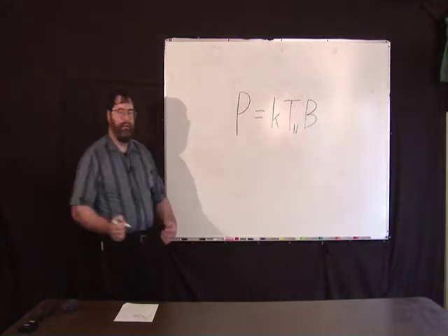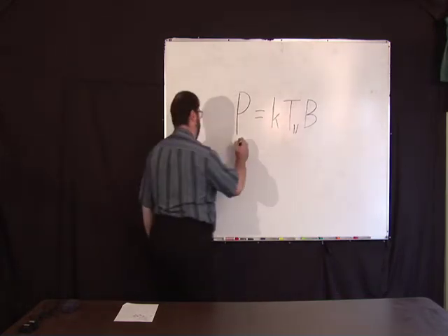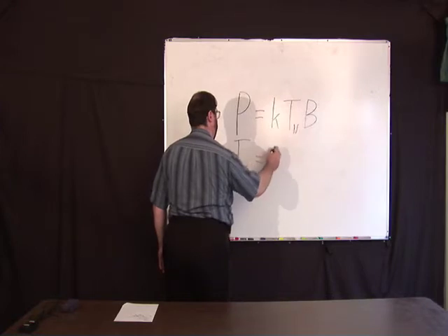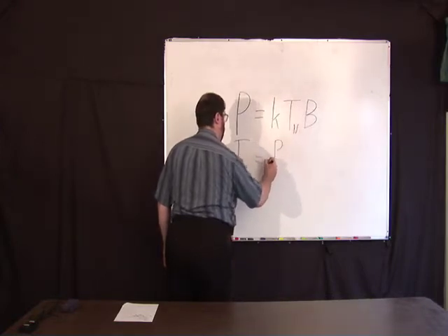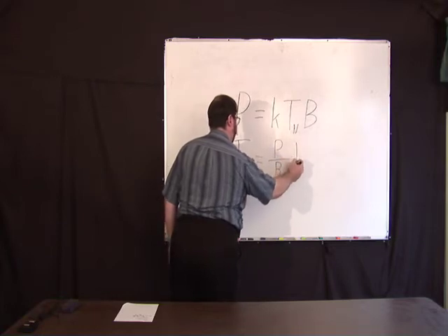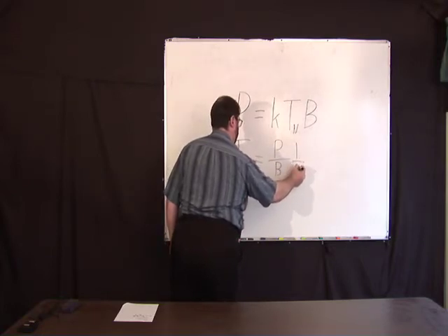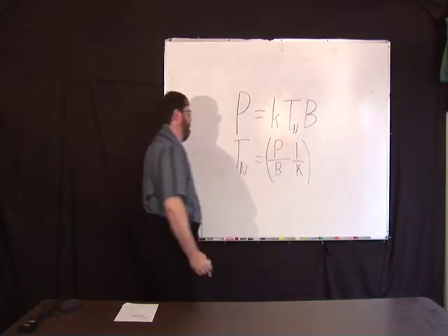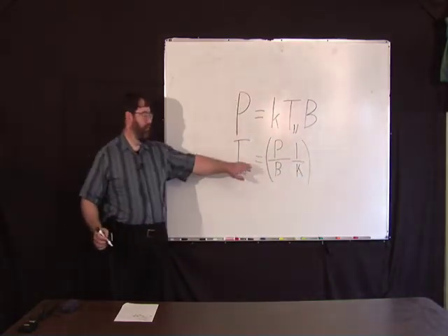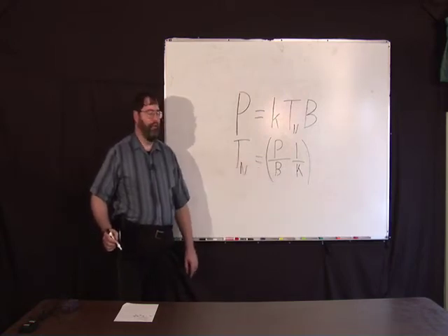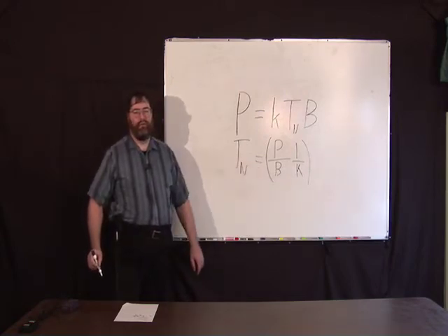Okay? The noise temperature, doing a little algebra, is defined as the power per unit bandwidth divided by Boltzmann's constant. So you measure some power per unit bandwidth, divide by Boltzmann's constant, and you get something called the noise temperature.